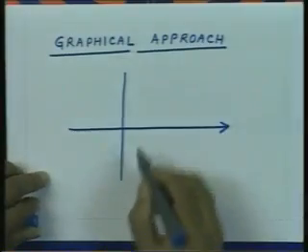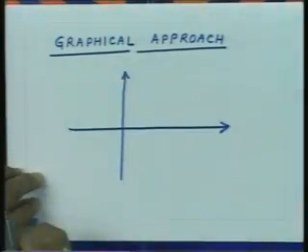We are not talking about negative resistances here, and the reactance could be positive, that means it could represent inductance, or it could be capacitive, so it will be negative. So, if I plot an impedance point on the complex impedance plane, the real axis represents the resistance and the imaginary axis represents the reactance.